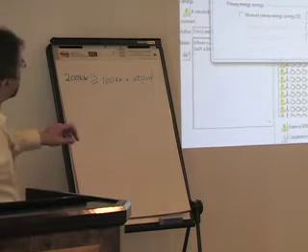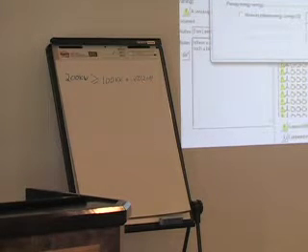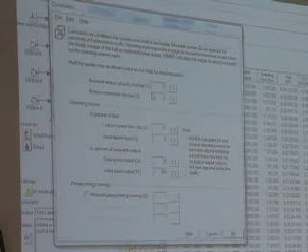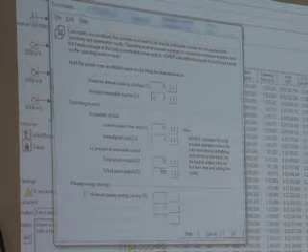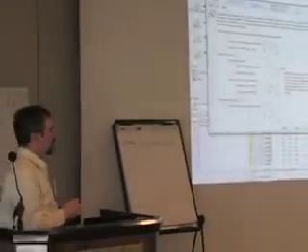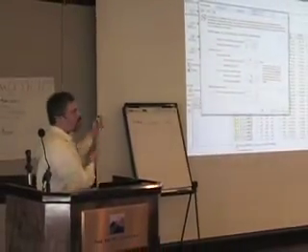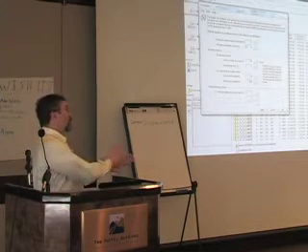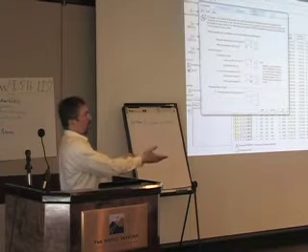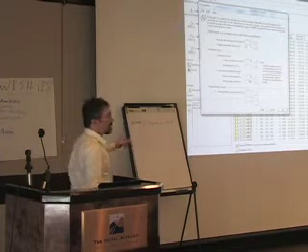And then we have this other parameter here that says maximum annual capacity shortage, which typically would be 0. So it tallies up the capacity shortage over the course of the year, and if it exceeds that constraint, it says, no, that system's infeasible. And it doesn't even show you the results, it just says infeasible system. Now, in the future, I think we're going to start showing those results anyway. But it's not meeting your capacity shortage constraint. But if you had a generator that you could dispatch, it would do that, so that it would meet this constraint.